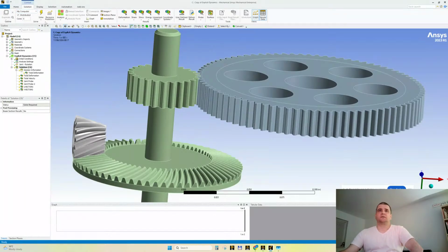And of course, my display is pretty big. It's 43 inches because I like to rotate and see in detail all the errors and the small elements. So this is what I advise: for a desktop computer, at least maybe 24 cores, at least 64 gigabytes of RAM, and one fast NVMe drive.